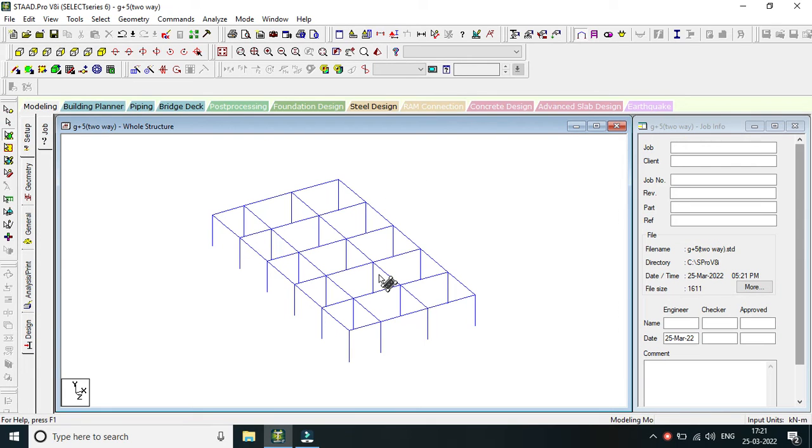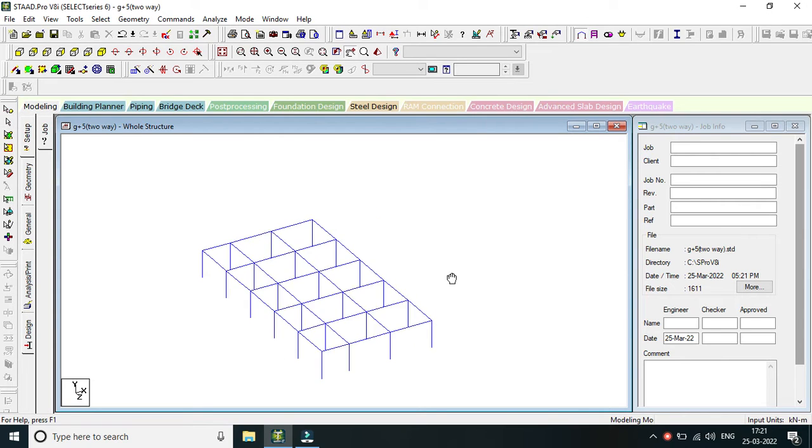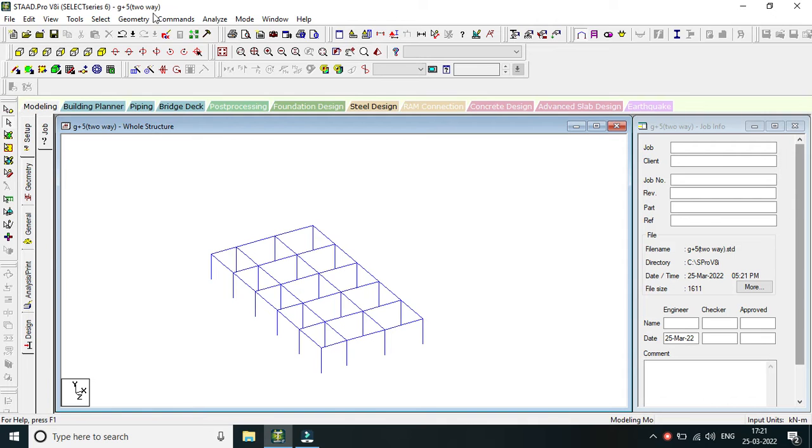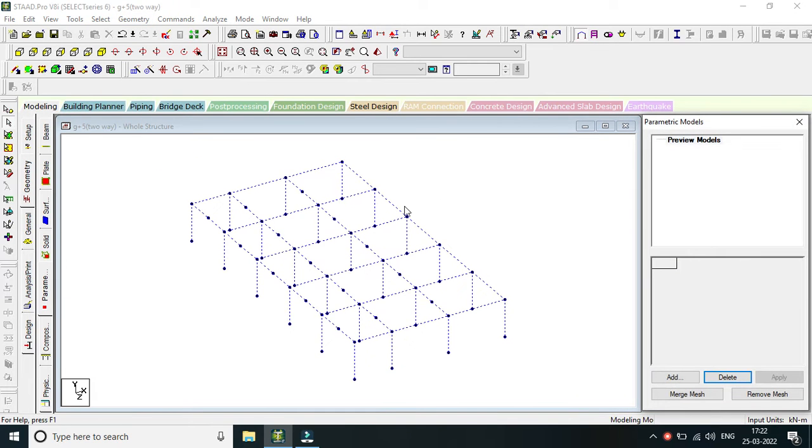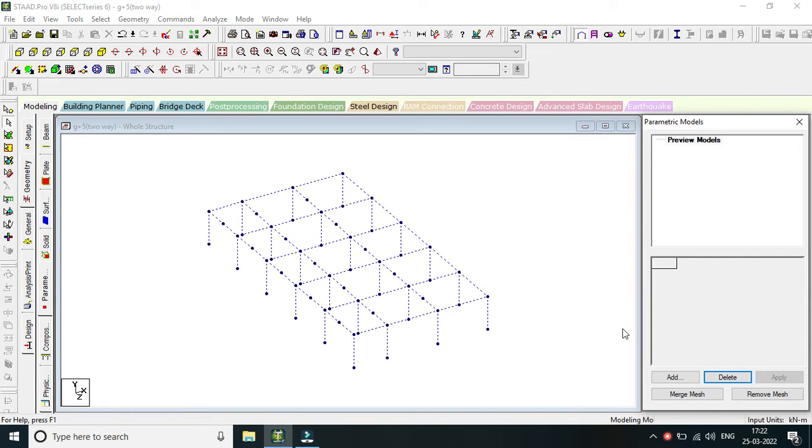these sizes are given in meters. Okay, so the default number of boundary edges, that is, how many edges should be there. Okay, so I'm clicking on this OK option here. Do you want to add openings? That means if you want to add openings, we can add. But here I am selecting no, so that our mesh will be created here. Okay, so let it be loaded.